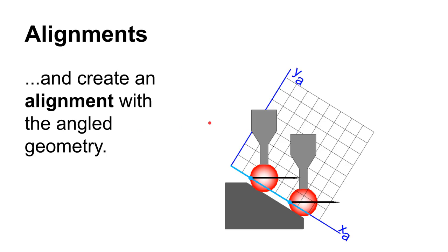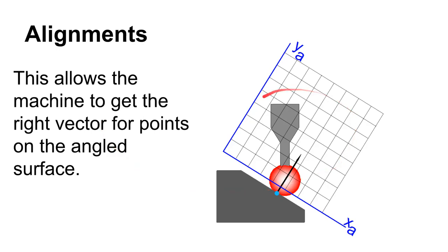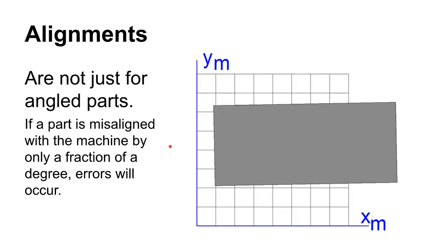So what you do with a CMM to set up where your X, Y, and Z will actually align with your part is to go through a procedure of creating these things called alignments. Okay, so notice that here, if we probe these 2 points, even though the points weren't probed exactly right on the surface, we can at this point say, that is actually an axis, and align the axis to that. All right, so that will allow us to set up a frame like this, and now we can actually jog and precisely probe points like that.